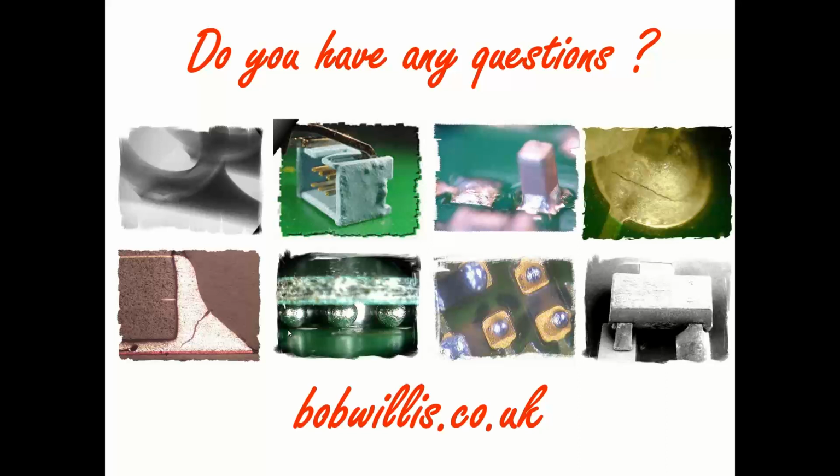Right, so first question. In the dipping video, there appeared to be dust on the board. Yeah, quite possibly. If it's a no clean process board, then yes, that's perfectly feasible. If you don't allow contamination on the surface of the printed circuit board, like flux or flux residues, which is quite common in automotive.